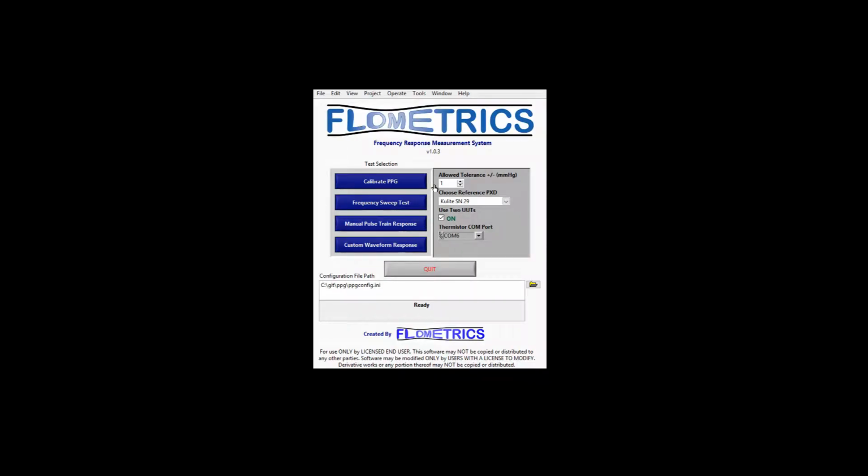Frequency Sweep Test. The Frequency Sweep Test function of the FRMS is used to analyze the natural frequency, damping ratio, attenuation, and other frequency response characteristics of a given unit under test. This function steps through the specified frequency range, recording the response of all sensors throughout the test. The results are then calculated and saved to a report for each test. Operators can also save a cumulative distortion report for all tests.